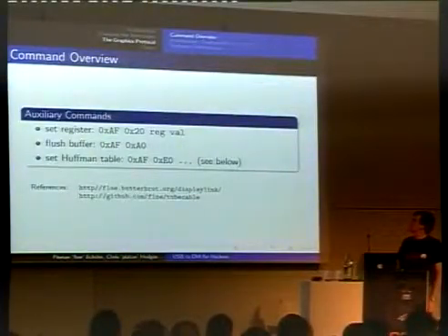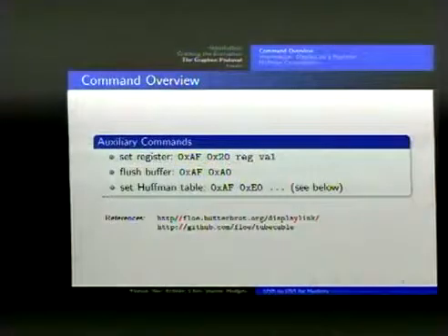You have a number of registers which, for example, determine where the frame buffer starts, so you can do vertical scrolling by just setting a frame buffer offset. Most of these values we have just taken from what the Windows driver sends to enable standard video modes.